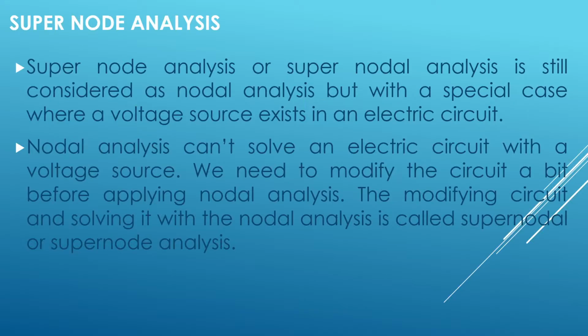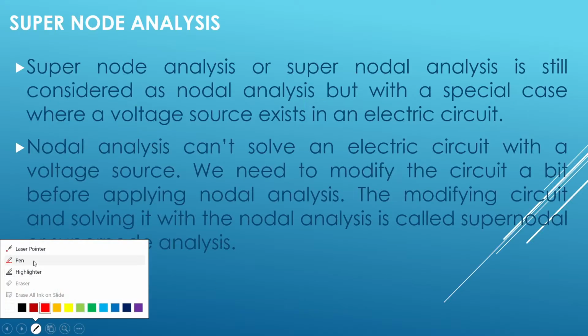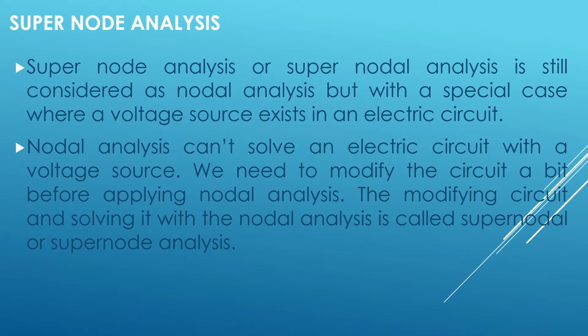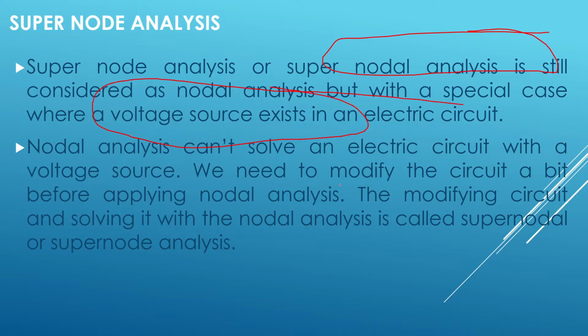Supernode analysis is still nodal analysis. The only difference is that there will be a voltage source which exists between two nodes. For that, we have to modify the circuit. If we modify the given circuit in order to implement nodal analysis, that modified circuit you can call the supernode analysis circuit.